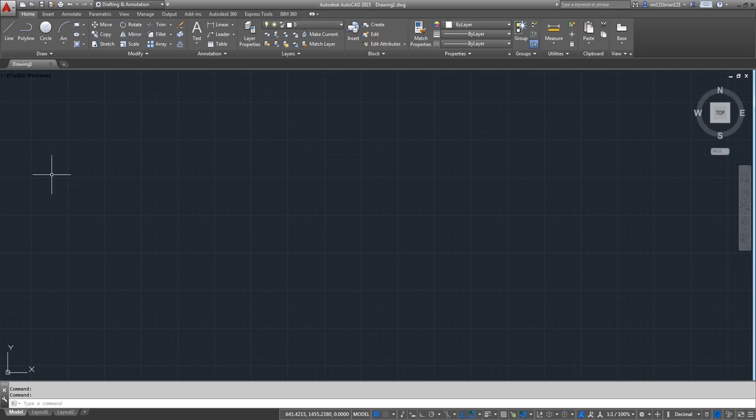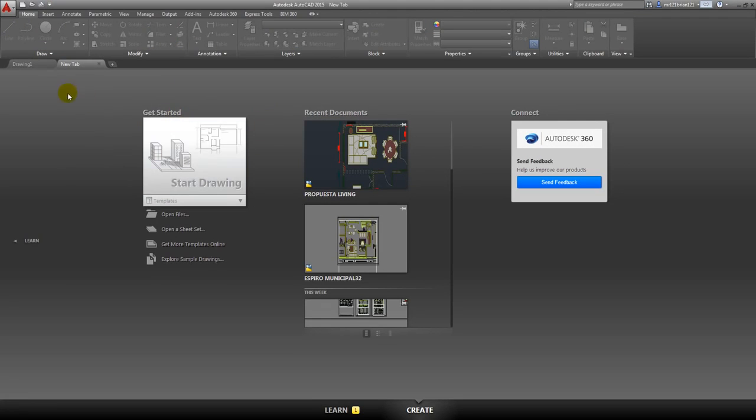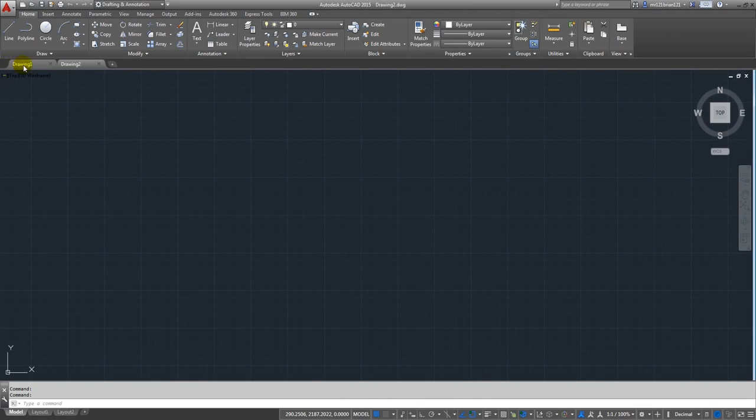If we want to make more drawings and don't close the main drawing, we can press the plus here, and it will make us another new drawing. For example, here you can see we can start a new drawing, and then we have Drawing 1 and Drawing 2. Then here at the lower part we have where it says Command. It means when we are using AutoCAD we can just press the icons we have right over here, or we can just type the shortcut and we are going to use the same command. For example, if I want to make a line, I can press Line, or I can press L, Enter, and make a line. We're going to see that in a couple of minutes.